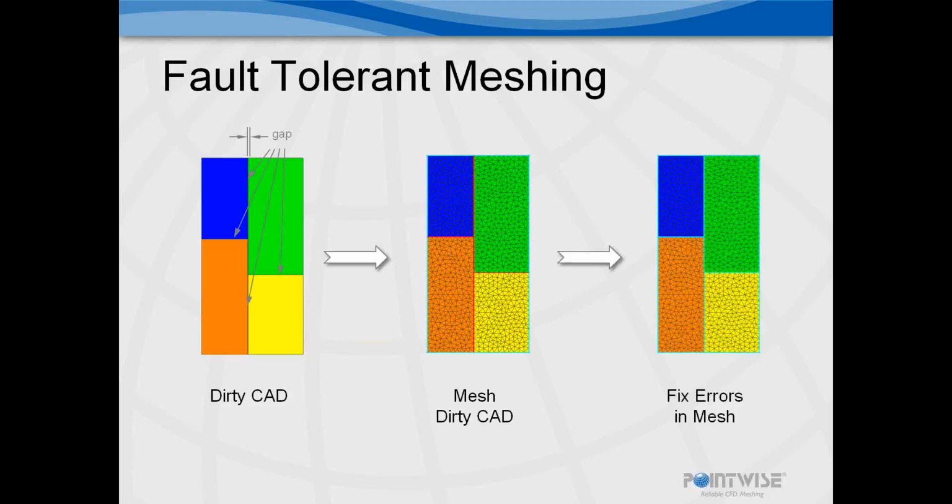Just before I explain the second method, I should point out the use of red and blue for the internal line colors. In a couple of the operations in Pointwise, you'll encounter red and blue curves denoting their status. The red curves, seen in the middle picture here, we call them lamina, and indicate an internal curve used by only one surface, indicating there is a gap present between the surfaces. Blue boundaries, we call them manifold, indicate the internal curve is used by 2 surfaces, and this means that there's no gap or overlap existing between internal surfaces. And this is ultimately what we're after.